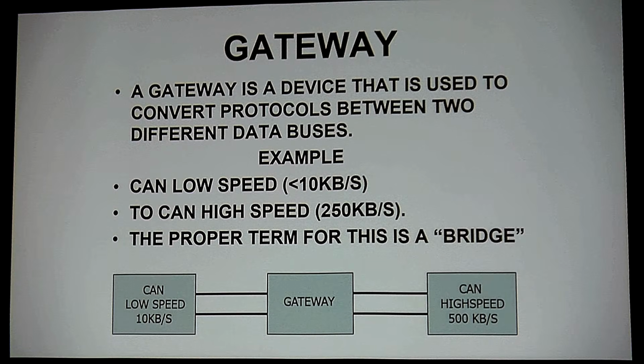It might be soon. Right now, it reports to what? An ECM, the engine control module. The ECM puts that data up on the bus. But I need it on the slow speed side of the bus, which is the driver information module. In order to do this, I have a bridge. This bridge, or gateway, is going to have my high speed connected with my low speed.